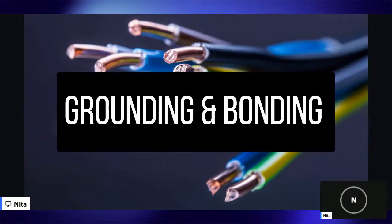Okay. Bonding is literally exactly what it sounds like. It's just connecting all of the metal parts in our electrical system, bonding them together. That's it. It's not any sort of confusing technical term. It just means connecting. It's like holding hands. We want all our metal parts to be friends so that electricity doesn't jump between them without us knowing. So we bond them together.